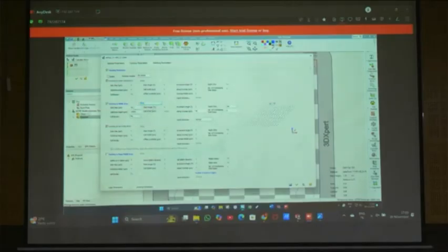And the side step means the distance between the hatch spacing, you can see these are the lines, right? Each hatch is there, that will go very fast during the printing, you can see how it is printing. So that is the distance between hatching. Suppose if you want to change this 50 to 45, we can change it. By default it is hexagonal, so I can keep it as rectangular, alternated means chessboard it is.